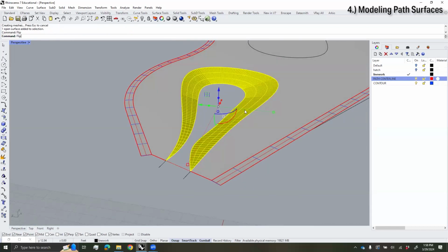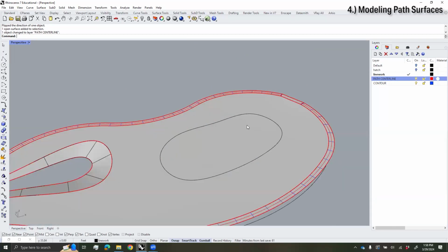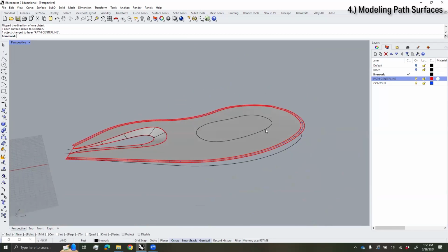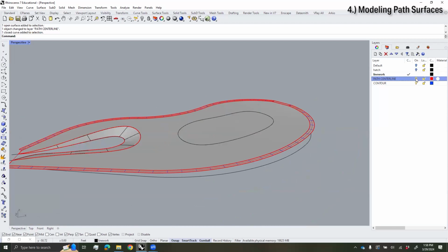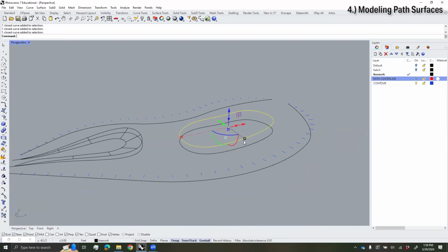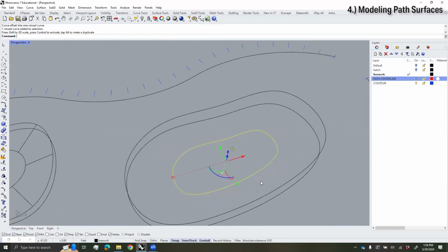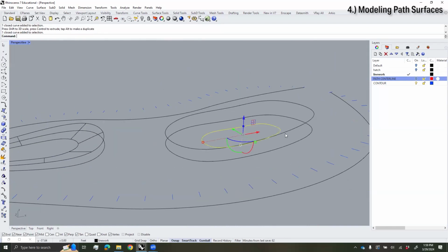If it's yellow, just flip it. Now that is one surface. So you want to make a little berm for this here. Again, I would probably use patch for this. Let me hide this. You have your projected curve there, but you also need the top of this berm. So I'll take this curve here and offset it, so that represents the top of the berm.